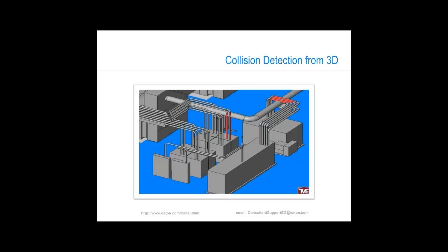One of the key benefits of the 3D element of BIM is in the form of collision detection. Collisions, or clash detection, occurs when building objects interfere with other building objects. And some really good examples can be found with electrical equipment, plumbing, and HVAC. These elements are typically not modeled or designed in the 2D world. And if they are, it's very difficult without using really good modeling tools to find these interferences.